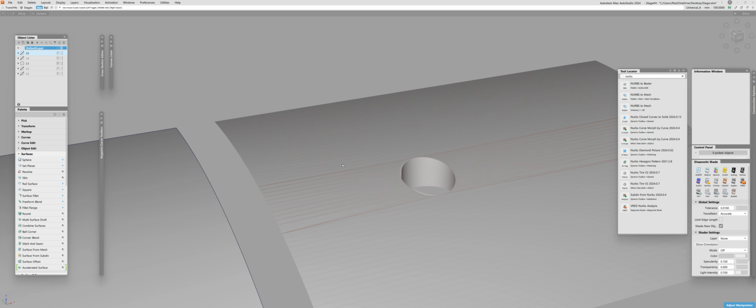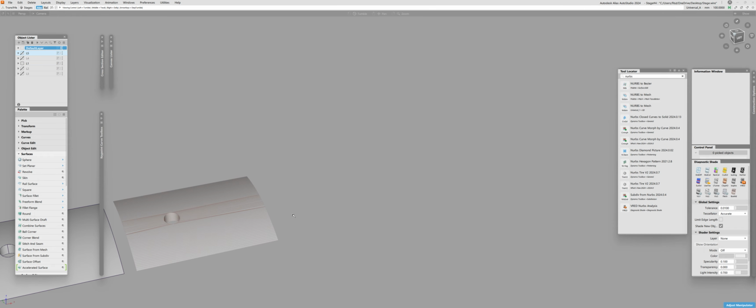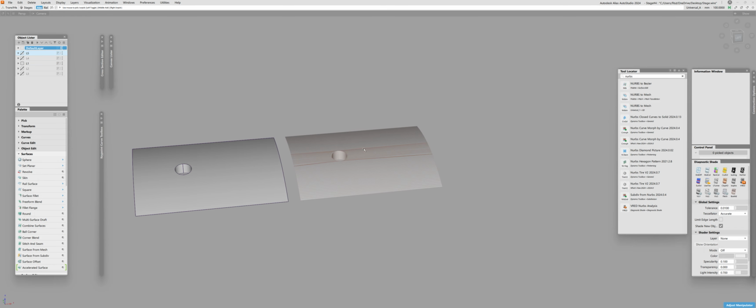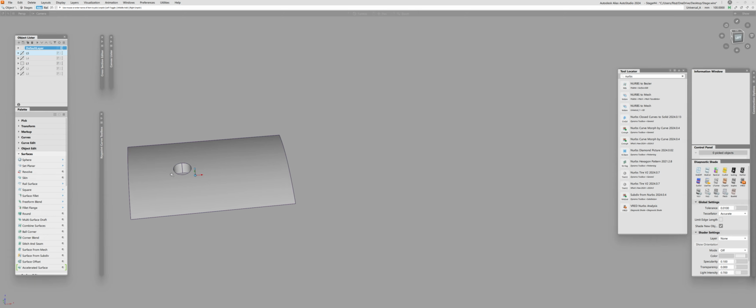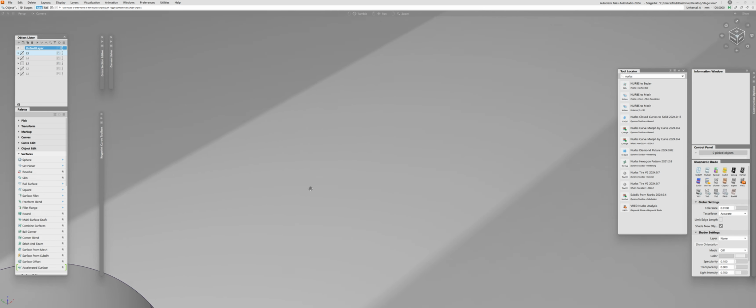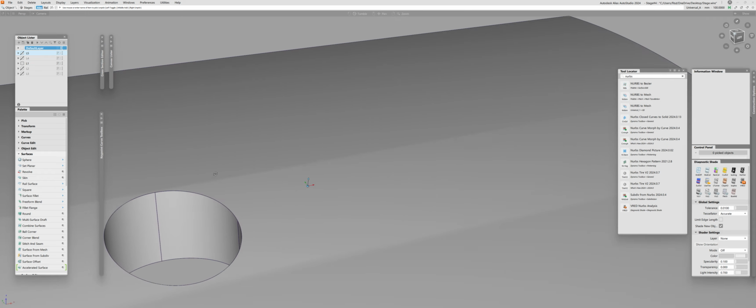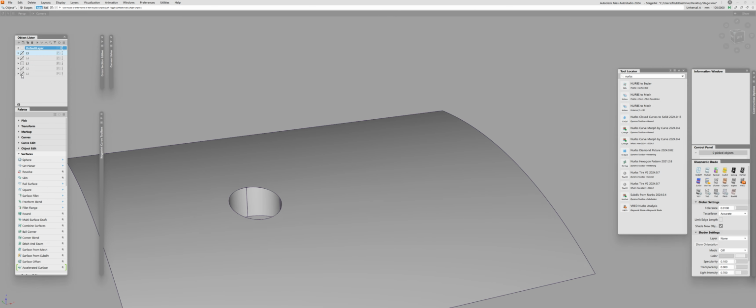Now another issue you may get is when you 3D print. At least what I know, there are no 3D printers on the open market which actually operate with NURBS geometry. They always operate with a discretized version of it, which is a mesh. So all the issues you have in your mesh, like what you're looking at, will be transferred in one way or another to your 3D printed model. So this is another issue you can get. But we are mostly focusing on visuals right now. Let me show you another example before we go to the ways to solve it.